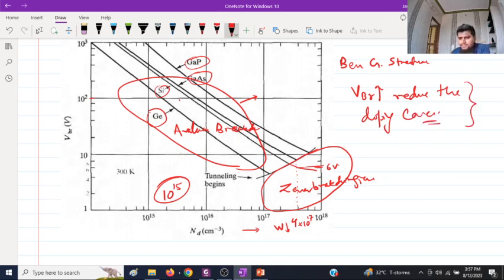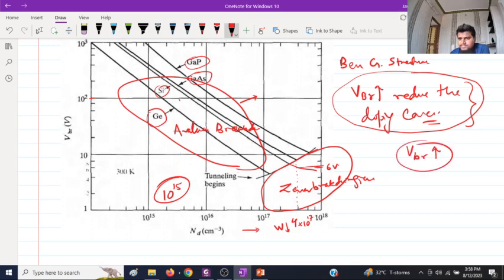That is also one of the requirements for having high VBR for space applications where the radiation is quite high. All the circuits which we send to space, like satellites and others, experience radiation fluctuation that is quite high, and that's why we must have a very high VBR rating. Some people also use wide bandgap materials for this application, because as the bandgap increases, this VBR increases.